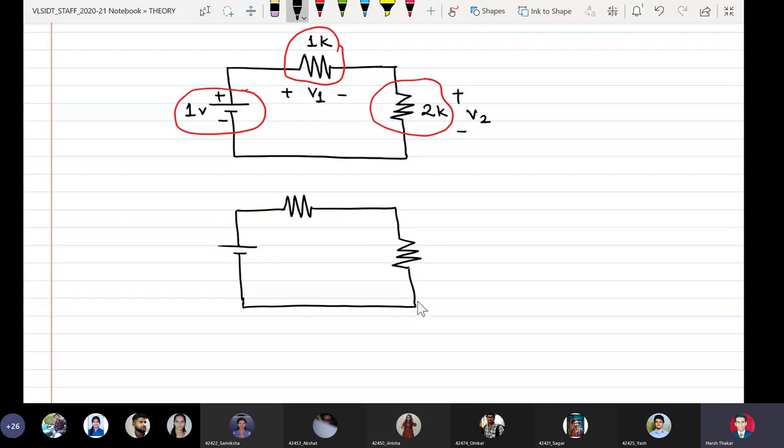So I have to identify how many unique nodes there are in the circuit. A node is any point in the circuit or network where there is either a voltage drop starting or a current division happening. So I can distinctly say that this is one node, and this is another node, because there is a component in between these two points. I said these two nodes are distinct.